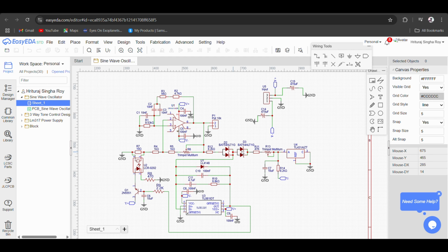And here the TL431 is not used as a shunt regulator, rather it is used as a minus 2.5 volt stable voltage. A part of the signal that we are getting in the output, we are feeding the rectified signal to this integrator circuit, which is controlling this transistor in here, and that controls the output of the LED, which controls the resistance of this internal resistor of the LCR. So depending on the amplitude received, it will control the resistance of the LCR.